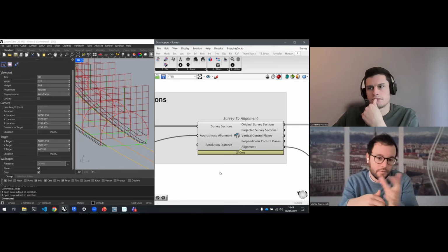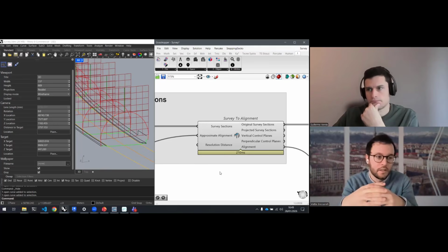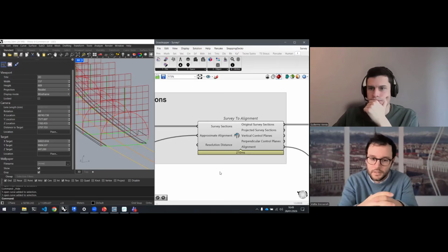You could use, for a better workflow, the Rhino Inside Revit plugin. If you use that, you can take the geometries from Grasshopper and basically bake them directly to Revit. In that case, that is a much better workflow, and what you get are native Revit families. So if you have to go to Revit, I would advise to follow Rhino Inside Revit, not really to use IFC, unless you just want a proxy to visualize. In that case, you can import it as any other IFC.